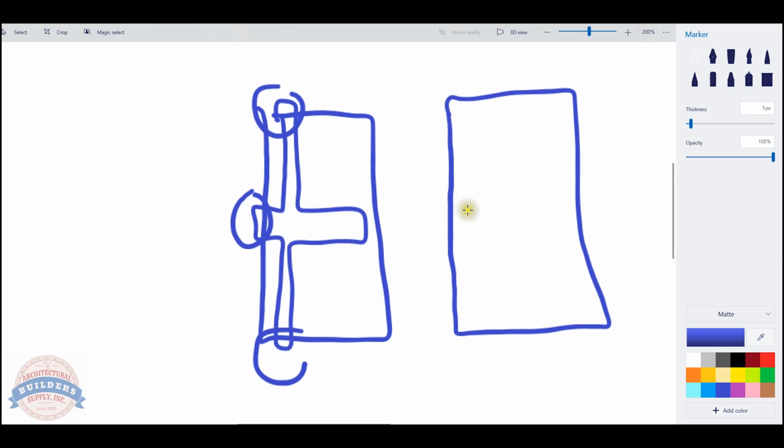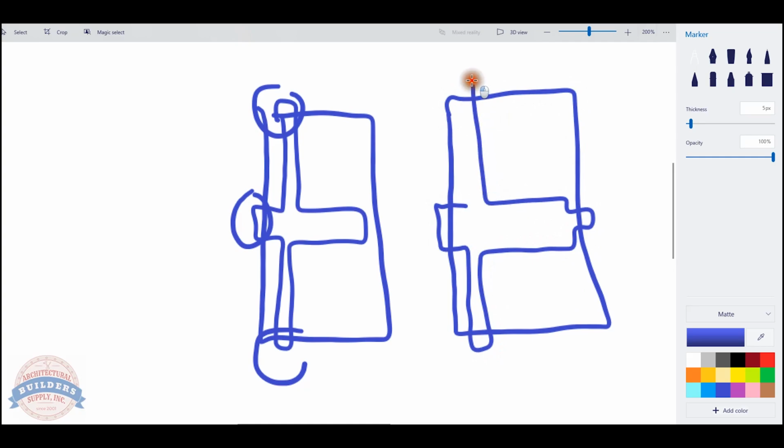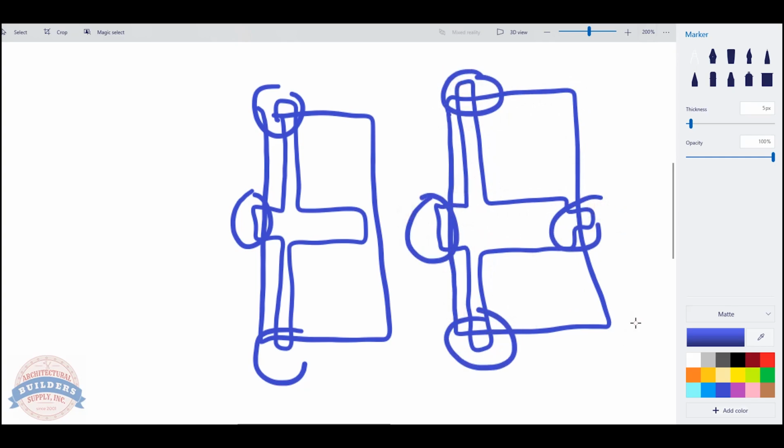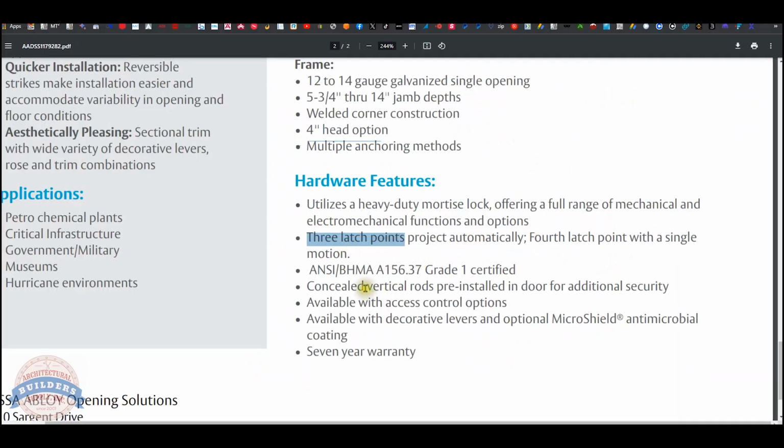Securitech, a company that is not related to Assa Abloy, produces a line of hardware that's very commonly used in military installations, but extreme high-end retail uses 4-point types of systems as well. We've been doing some projects for very high-end retailers, and they've got thousands of dollars worth of exit devices that are latching top, bottom, and on both sides to protect the extreme amount of street value of handbags and whatnot that's stored in the retail space. So you'll see those.